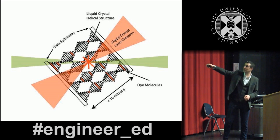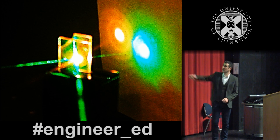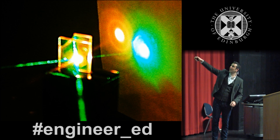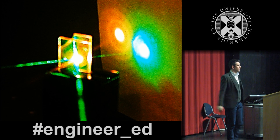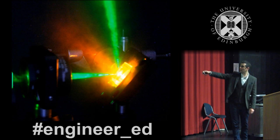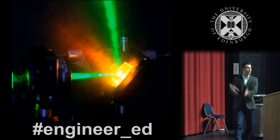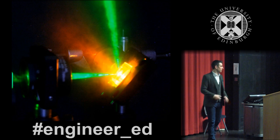You can see the two pieces of glass, in between, a 10 micron thick layer of liquid crystal. This is the pump light, the green light coming in, some green light going through, and the red light here, which comes out perpendicular to the substrate in both directions. If I want to, I can make it a single-sided emitter. I put a layer of aluminium on the back, make it reflective, and now we've got pump light coming in, some wasted pump light, and this red cone of light comes out, and this is a diffuse cone of light which we can collect and then use for something useful.